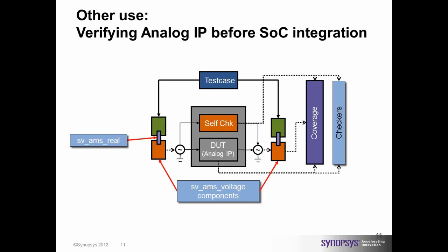Once you have your base transaction available, that's the bloodline of the entire test bench, and each of these drivers, generators, coverage collector, checkers, and monitors talk in that language, in terms of UVM-AMS real, and talk to each other with that particular object to provide various capabilities, such as coverage, self-check, or driving a node with a random value.